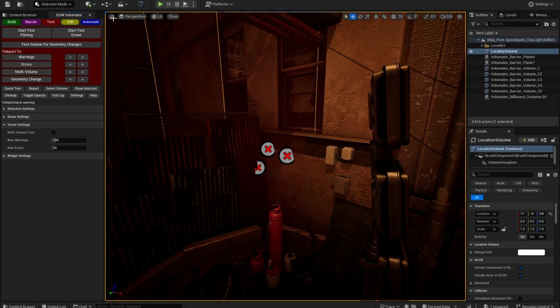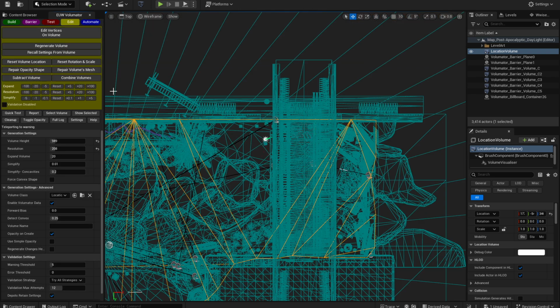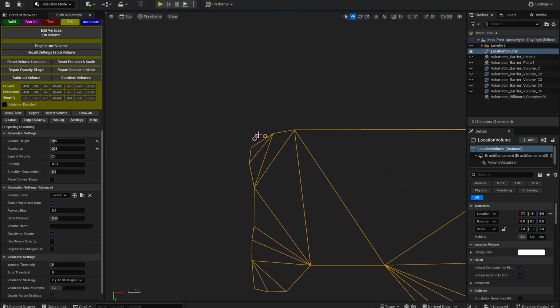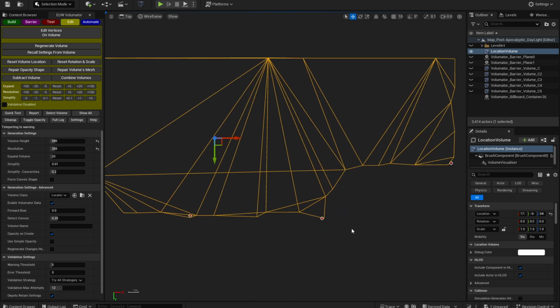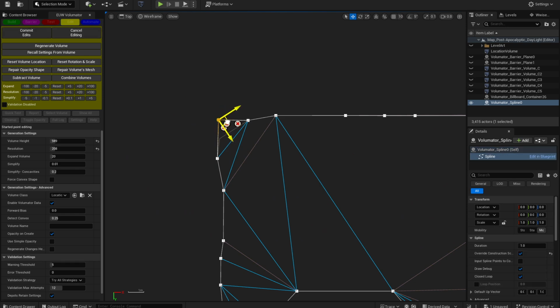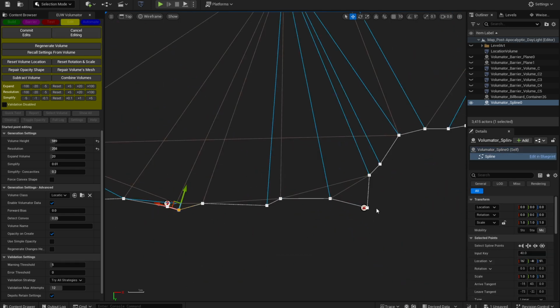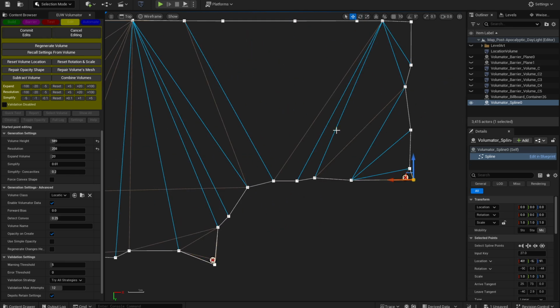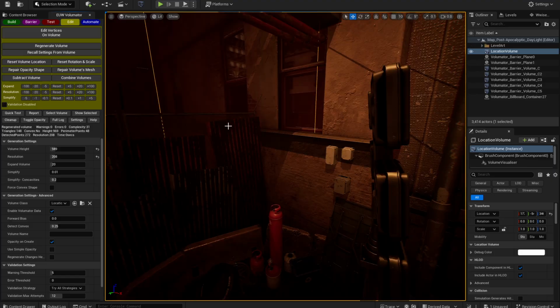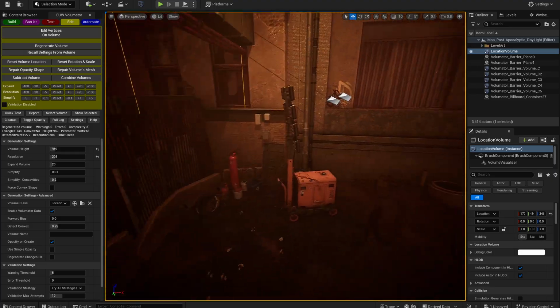But using this data, we can actually edit the volume. There's a video on the edit panel here, but just to very quickly show you how you can do this, if we go to show selected again, and really quickly here, we can see the errors. This is the top-down view and the volume here. And so we go to edit vertices on the volume and then move the points so that they now cover the shape. We hit commit, and there we go. All of our errors have gone, and our volume is now perfect with 0 errors and warnings.